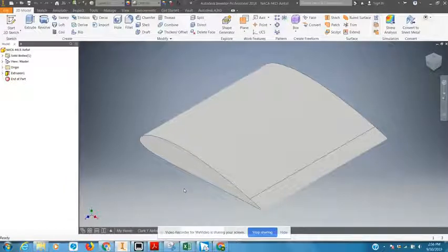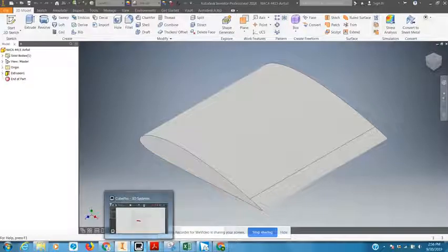And now I am ready to import that file into our Cube Pro post processor that'll convert the standard STL file into the Cube Pro format that will be necessary to perform the 3D printing.